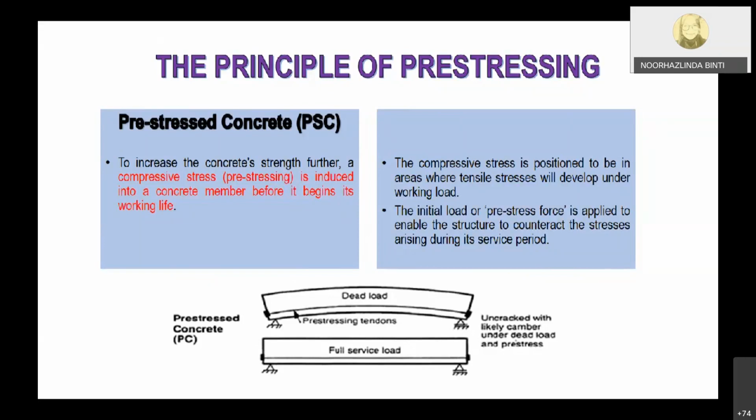So during the construction, we introduce this compressive stress inside the concrete. So where to position this compressive stress? Of course, in the area of tensile, which is the bottom part of the concrete itself. It's quite similar to the RC concept.